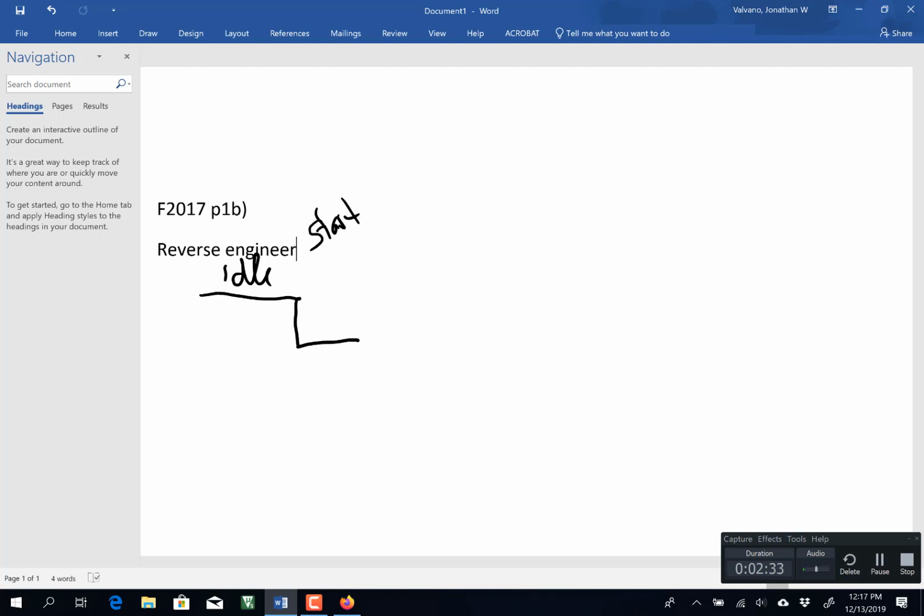Question: is it always 8 bits that are transmitted? Okay, that's a great question. He said, is it always 8 bits? The answer is, in 319K, it is always 8 bits. On the TM4C123, you have the option of a 9-bit protocol. On other microcontrollers around the universe, you can go 4 to 15 bits, but 8 bits is what we're going to do in 319K.